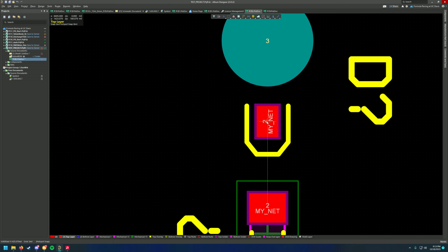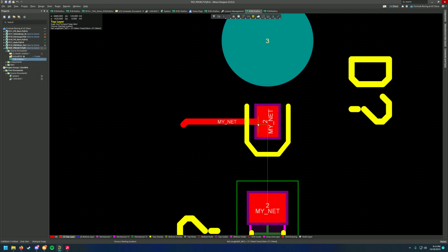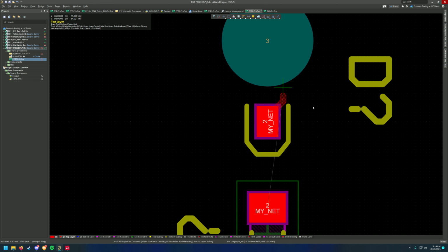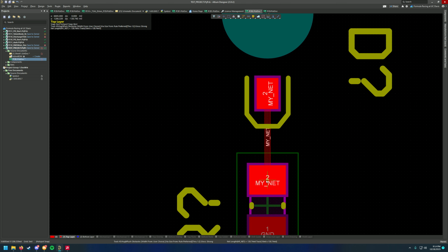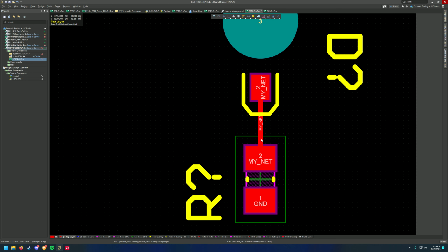And if you click on the first pad, then it'll start drawing. This is going to be a copper trace ultimately when you get the design back. So you're now making a copper trace. Start that over. So Control W, click on your starting pad and you'll start drawing. And then you can just go down and click on your next pad. So this was a pretty easy connection.